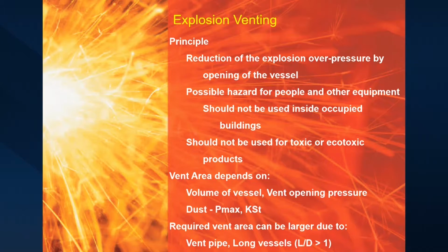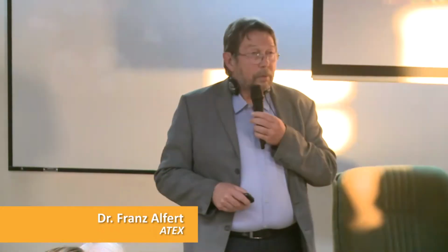And of course, also when we have elongated vessels, then we can have much stronger explosions, and therefore we have to take that into account. We have also put that into the NFPA 68 and into the venting standard in Europe: vessel L/D influences the explosion, and we have to take that into account.